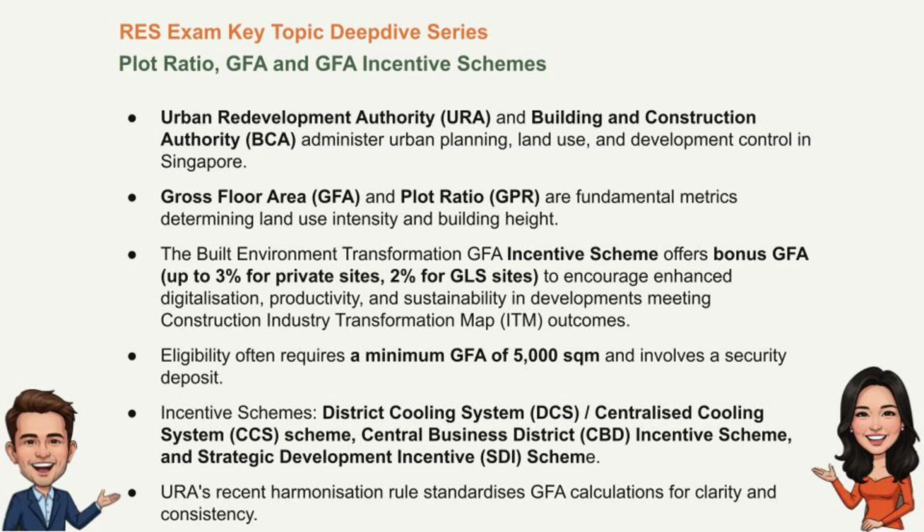So tying this all together for our RES candidates listening, why is understanding this whole interplay, GPR, GFA, height, density, constraints, why is it so absolutely vital for them, for the exam and beyond? It's vital for several key reasons. Firstly, assessing potential. If you're looking at a site for redevelopment, maybe an en-bloc sale, you need to understand the realistic buildable GFA and height, not just the theoretical max. That's what developers will base their bids on.